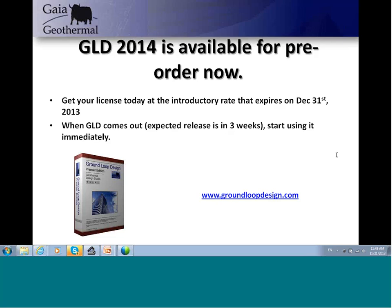A lot of people do a lot of different kinds of things. I would say when people are designing typical pure geo systems, the typical range of target entering water temperatures is probably in the 85 to 95 degree range. Some people aim for 100, some people aim for 75, but the most common is probably 90 degrees plus or minus 5. But if you're working with a hybrid system intentionally, and the hybrid system is going to come on, you have some more flexibility in terms of what you're aiming for. Maybe you do want to aim a little bit higher. Of course, the higher you aim, the more it is going to reduce the performance of your system.